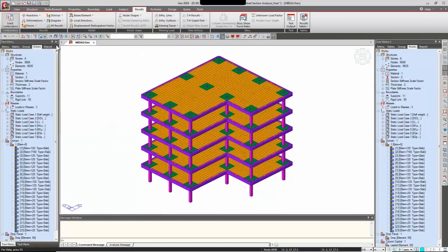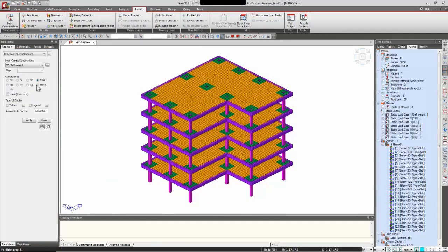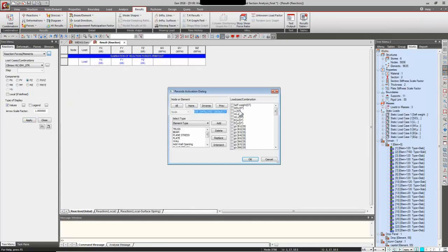And we will go ahead now to checking the reactions. We can get the reaction forces and moments on our workspace. We can simply select our maximum strength envelope and let's see the vertical reaction. These are the values, and the red one shows that the maximum reaction has been obtained at this location. We can click over here on this three dotted box for every result and get our results in the form of tables.